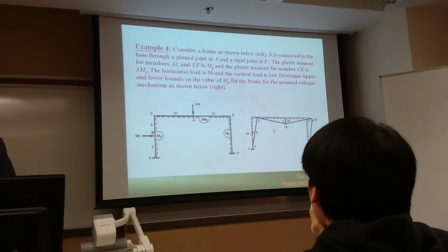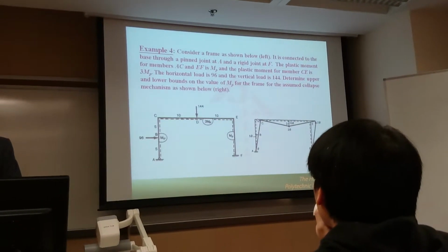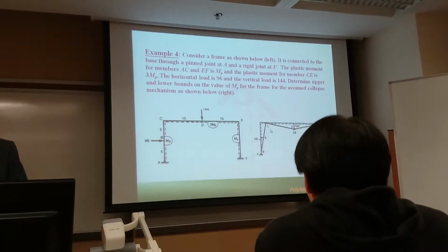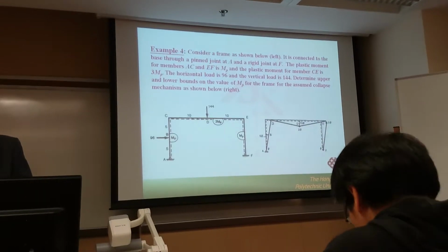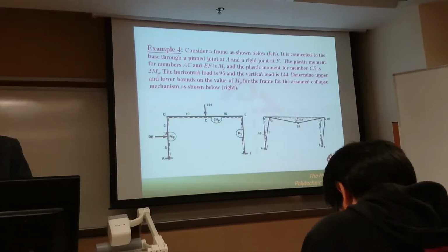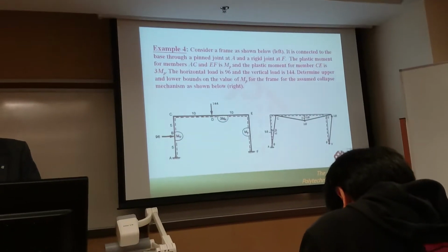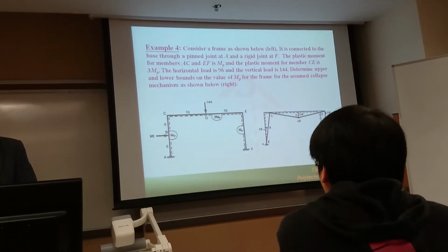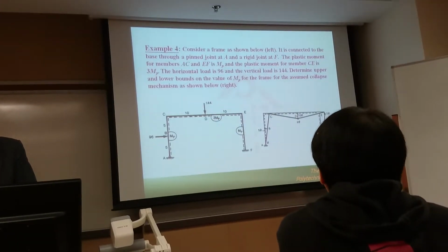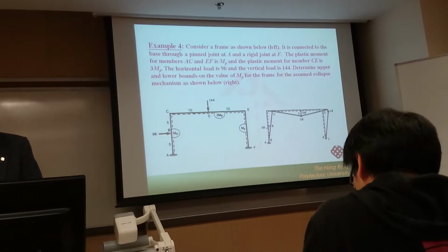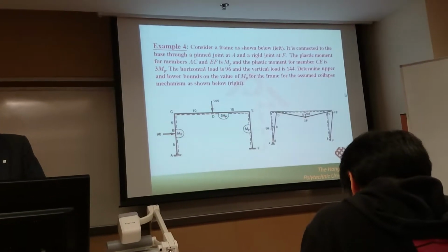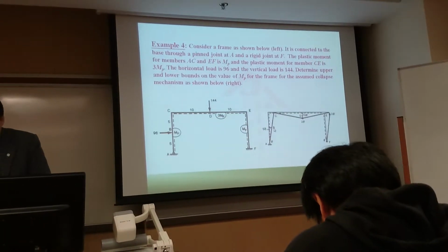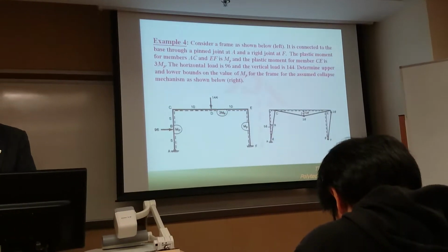In this case, the other possible plus hinges are located at point C and point B, because point C is a connection, so it is a possible plus hinge, and point B is a force application location. So according to rule 1 or rule 2, it is a possible plus moment location. So you have to calculate the moment for section C and the moment for section B.